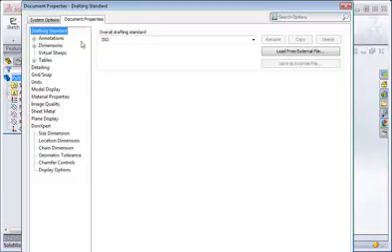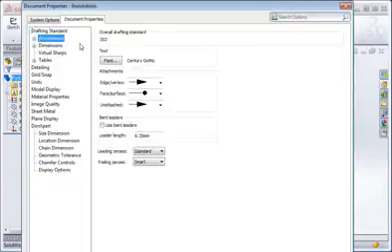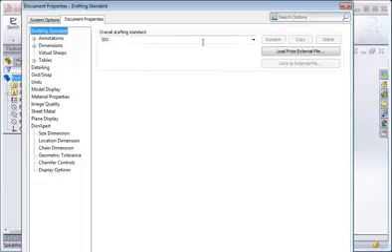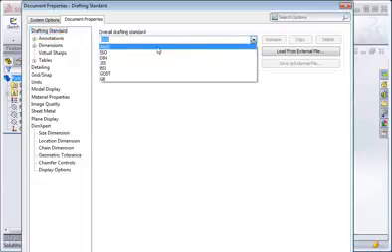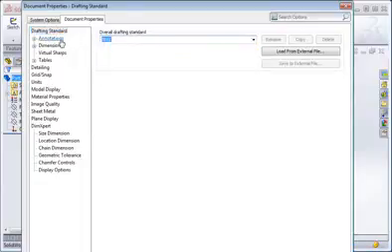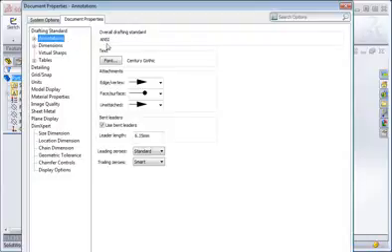We're going to create a template for part files that use the inch unit of measure and the ANSI drafting standard. And the overall standard controls all the settings on this dialog box. It's currently set to ISO, and if you click Annotations, you can see that annotations are controlled by the ISO standard. Click the drafting standard, and then change the overall standard to ANSI. Now if you browse through the settings, you can see that they all use the ANSI standard.